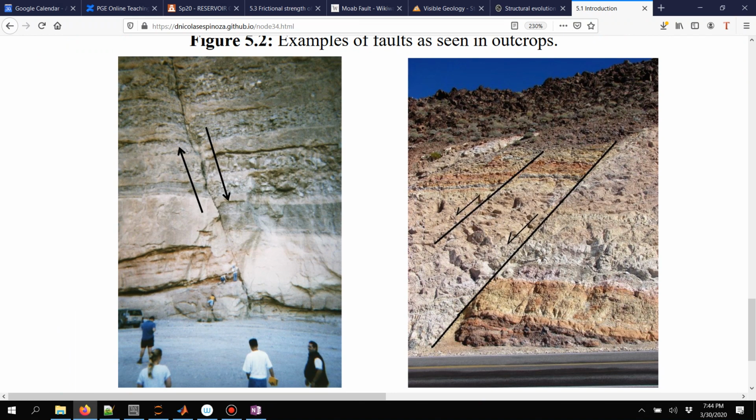One more thing that I like to say over here is that usually for normal faults, you would expect the hanging wall, which is above the fault, to move in the direction of gravity, moving down. In a reverse fault, you see the opposite. You see the hanging wall moving up, opposite to gravity. In this case, this is a normal fault. So in this case, you might be tempted saying, oh, okay, I know this is a normal fault, so I'm pretty sure that right now in this place, there should be